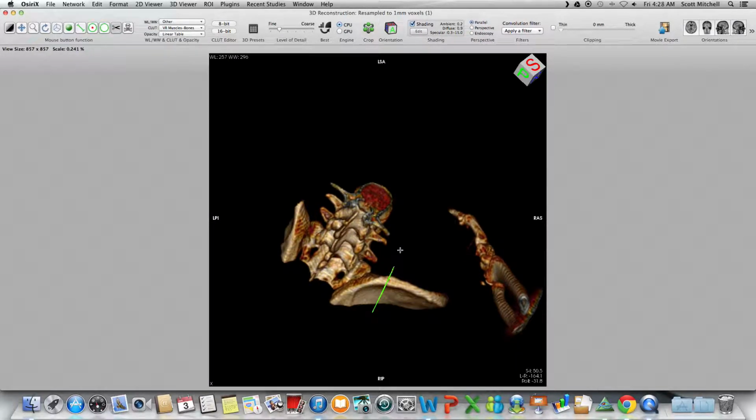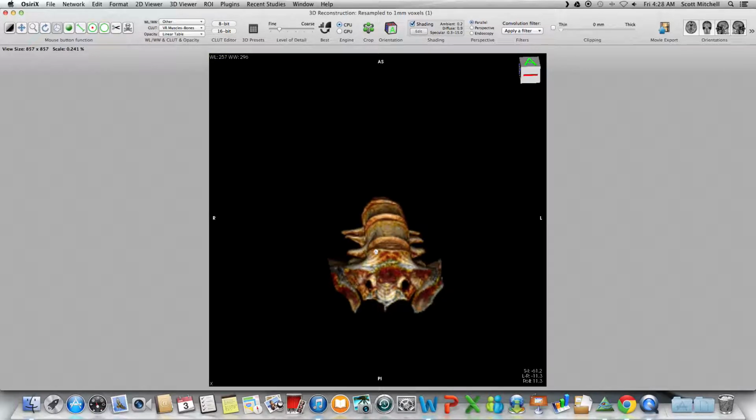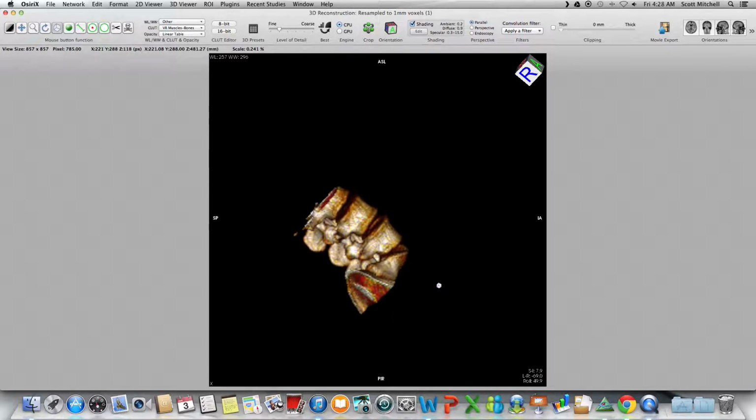That's what I'm going to be doing for the next few minutes. So here we go. Delete. Also, you can use these little keys up here to help you orient yourself. The other thing that you can do, since this is a region of interest, is a reverse scissor. This is an area that we like, so I'm going to highlight it and click enter. Everything outside of that lasso is cut. Between delete and enter, you're going to be able to do basically all that you want as far as getting rid of excess stuff.